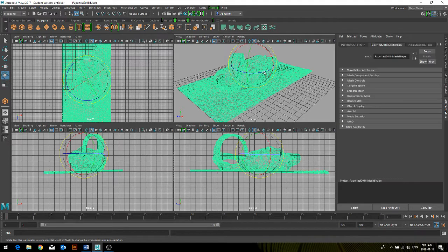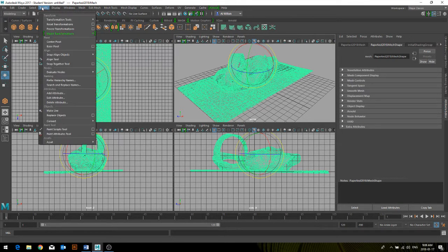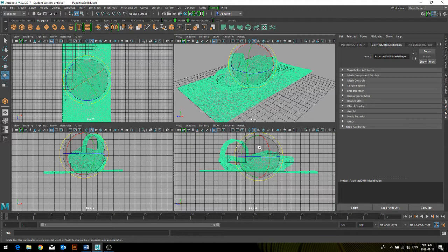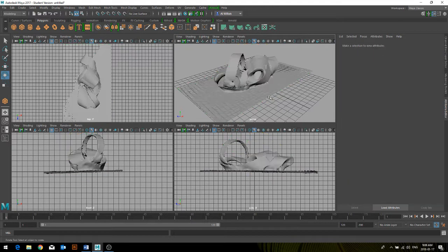Sure, of course. If you click onto your object and go under the Modify tab, you'll see Center Pivot, and that will bring it to the center of your polygon. Sometimes when you bring it in, the pivot is off to the left or in a corner, and then when you're rotating it around, it disorients you. So I find that this is a little bit more effective.